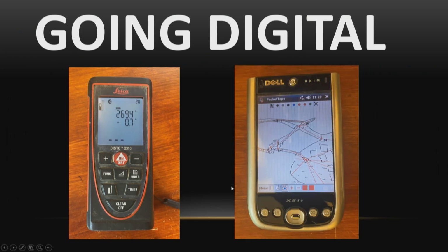And the data, with some research into blunders in cave surveying, found that with somebody licking and then reading a tape measure which is covered in mud, shouting out the numbers to somebody else who's writing them down on a muddy notepad with muddy hands, and then taking it out of the cave and transcribing those numbers into a computer, there are so many opportunities for blunder that you get an error in maybe as little as 1 in 10 or fewer readings.